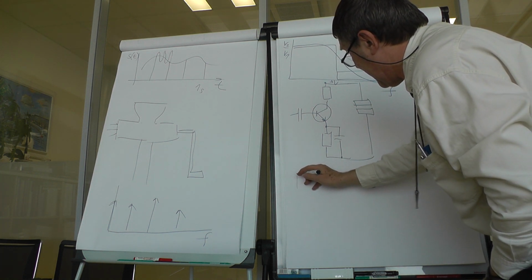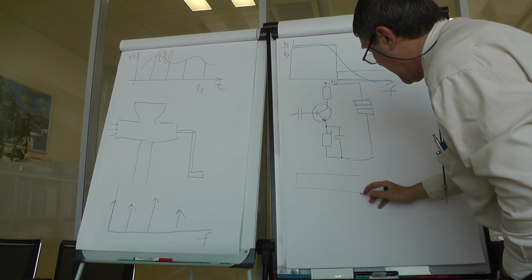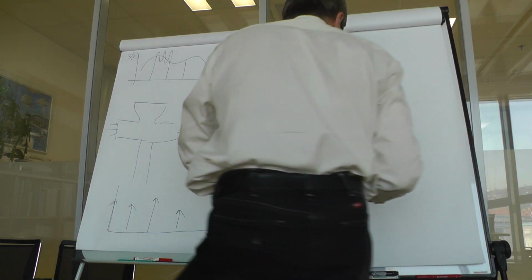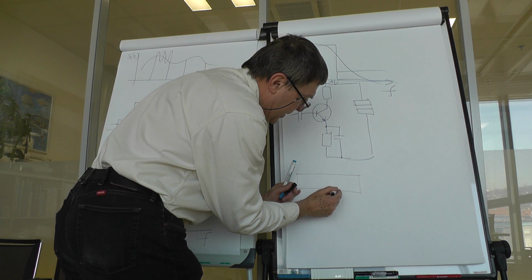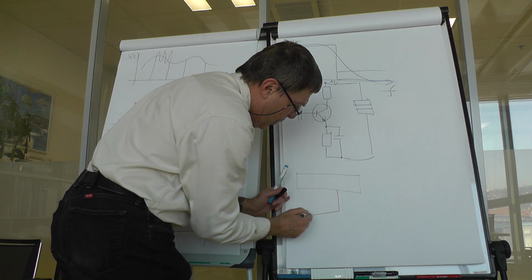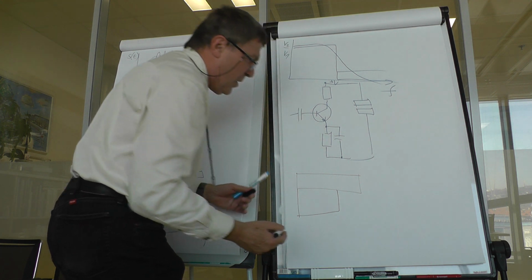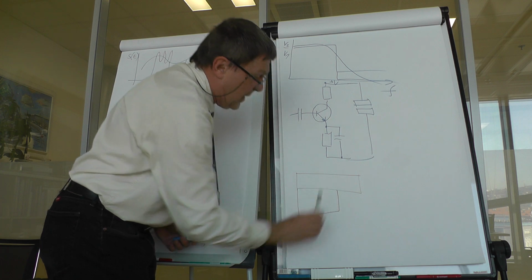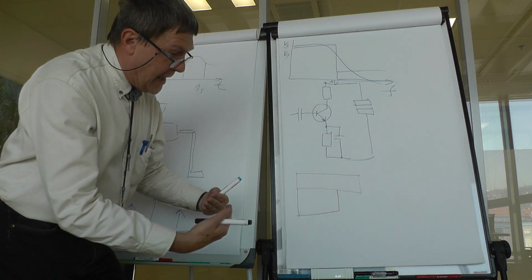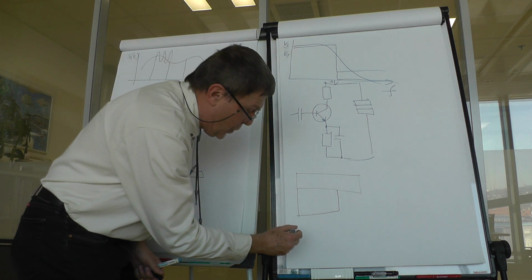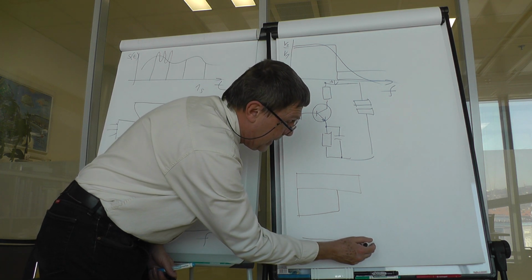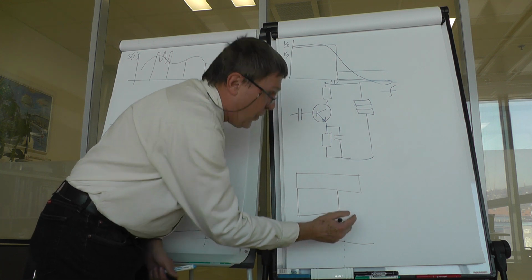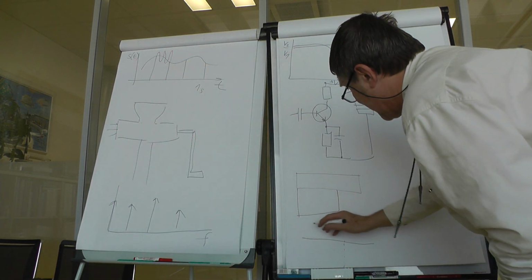If you have a signal in the frequency domain which has, for example, this bandwidth, but you sample it only with the number of samples or period of sampling relevant to this frequency window, you get a strange signal. You get the frequency signal mirrored, and what you in fact get is this.